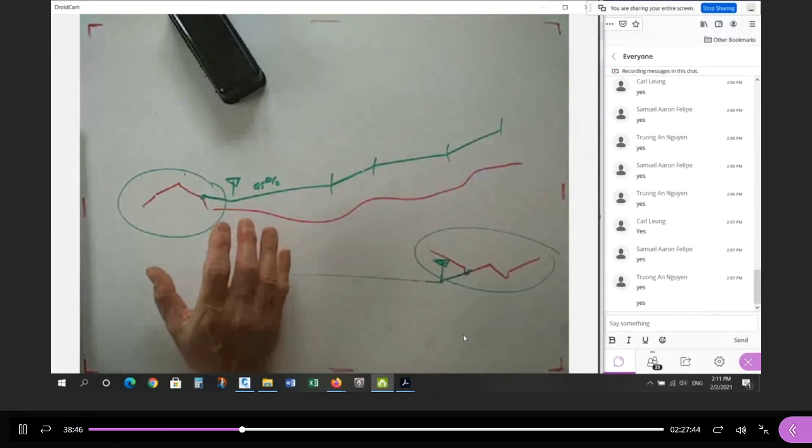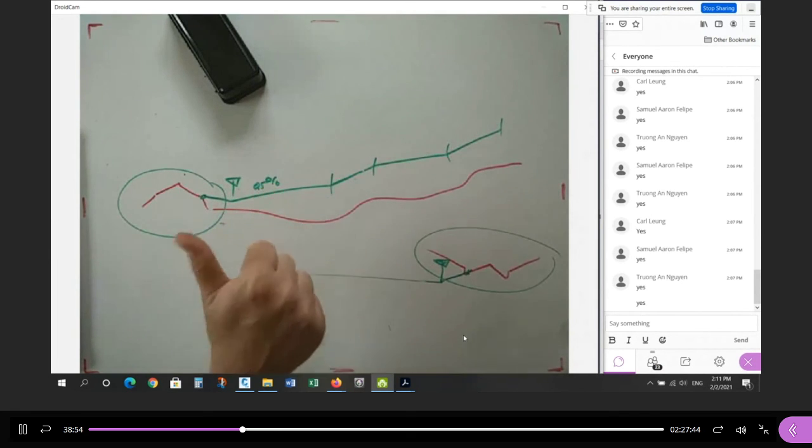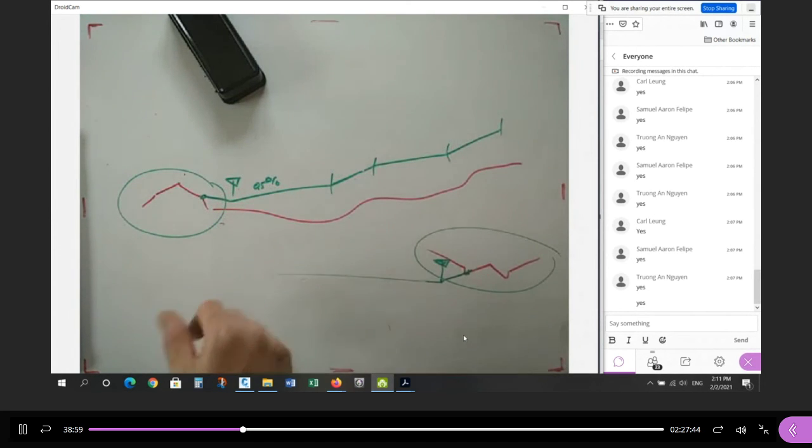So if I assume that the design is existing, that should be close enough to what was actually built. Okay, and that's what I want to do. So to do that, I need to create those 3 building blocks: plan, profile, cross-section of Ledger Way, so that I can create the model for the corridor, I can create the surface for the corridor, and then I can use that for my design.